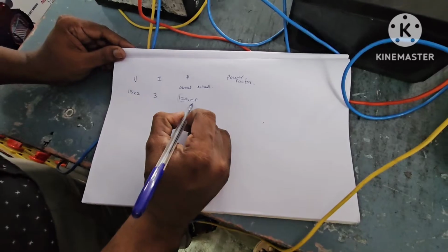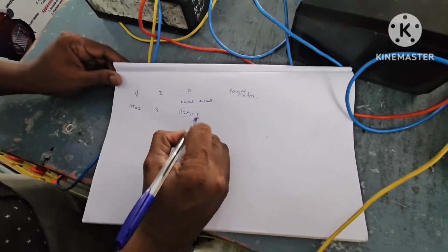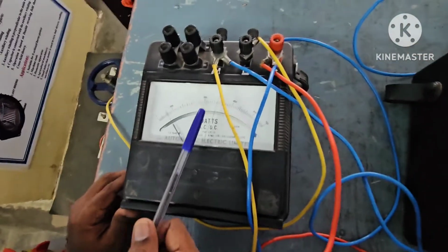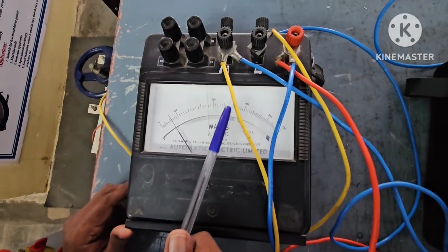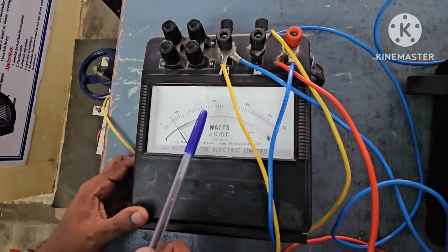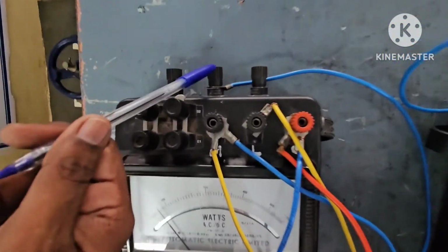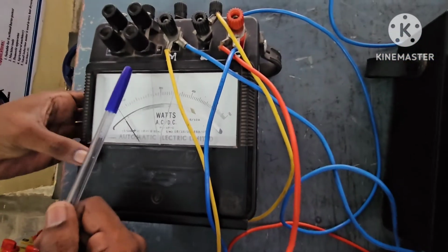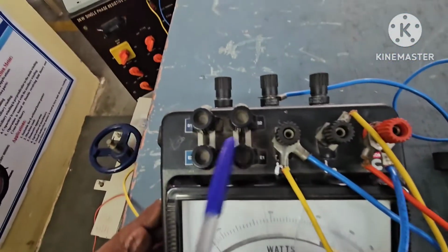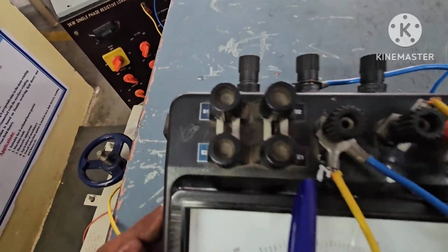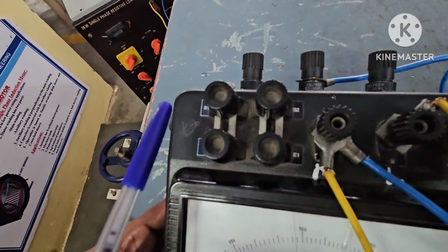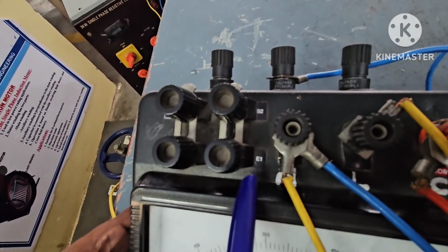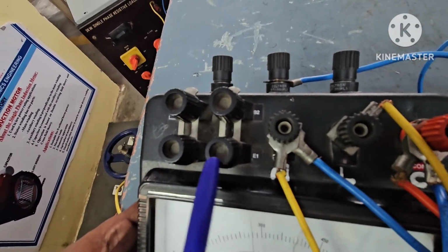which we specifically use for the wattmeter. So let's see how to identify the multiplication factor for the wattmeter. That needs to be decided based on the voltage and current rating of the wattmeter. We already know that in this voltmeter we took the 300 volt range. So voltage is now 300 volt. Now to see the current rating, you need to see this terminal, how the B1, B2 and E2, E1 are connected. Look here, B1 and E2 are connected, and then B2 and E1 are connected. So this will give you the current rating of the wattmeter.